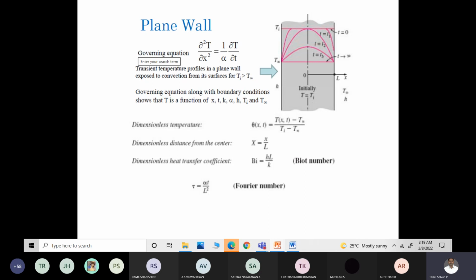The thickness of the wall will be small, whereas the length and the height will be large, especially in a multiplex complex. We can measure the wall thickness, but the length and height are almost infinitely long. So those types of walls, in which we consider the heat transfer, can be assumed to be an infinite solid.